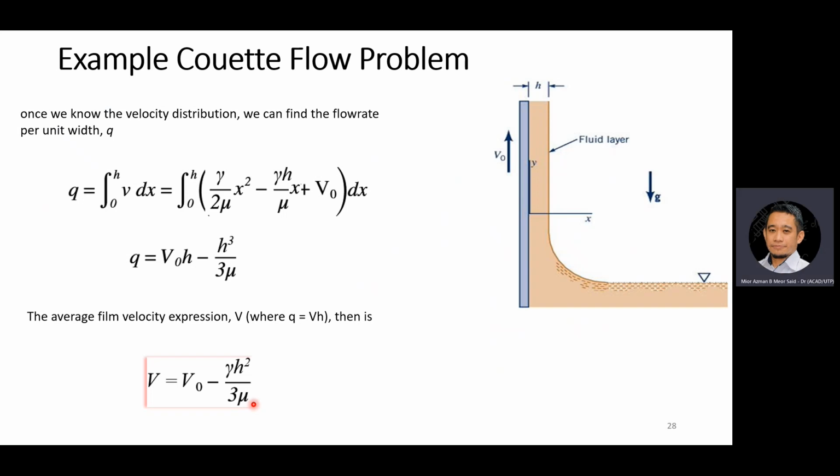Okay, so I think that's all for today. We have solved the Navier-Stokes equation. First, we simplify it, and then we solve for the velocity expression, where we look at the problem case by case. Depending on the problem, we put in the boundary conditions, and then we solve for the velocity profile, or velocity distribution, or the formula for the velocity. Once you have the formula for velocity, you can use that to find other parameters such as the mean velocity or the volume flow rate.